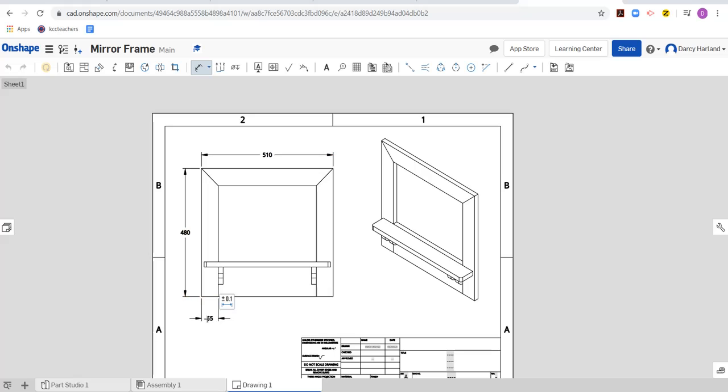Generally, a rule of thumb is that you will want to put as many measurements on your page as you will need, just at least once. The fact that I've done this 65mm measurement, I can bring that 65 to be outside those lines there. I don't really need to show this one to be 65 because you can obviously tell it's the same thickness as this piece here. So showing that once is plenty.